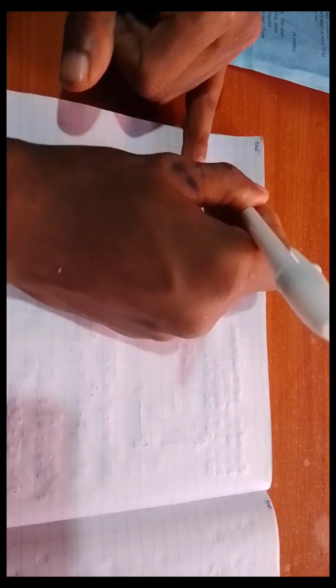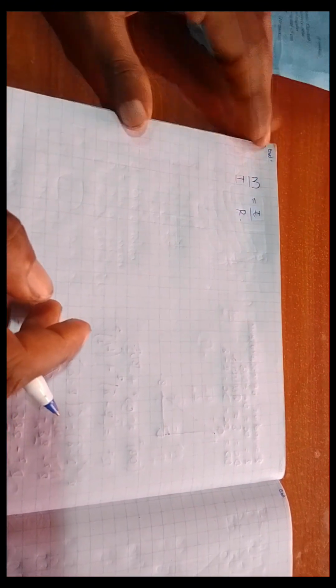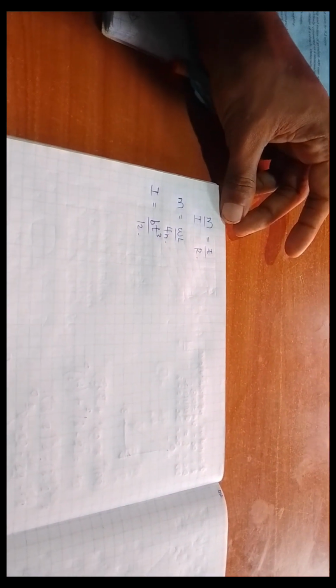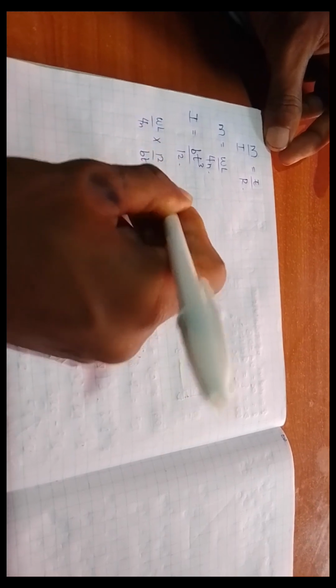To derive the deflection, you equate the moment over the moment of inertia to the modulus of rigidity over the radius. Having used this, we know that the moment of this semi-elliptic leaf spring, as we had derived it, is WL over 4N. We also know that the moment of inertia of a rectangular section is BT raised to power 3 all over 12. So we substitute this into the formula. That is WL over 4N times the reciprocal of this, 12 over BT raised to power 3, is equal to the R which we have just derived.